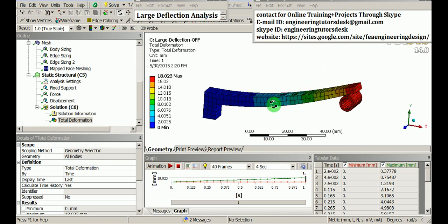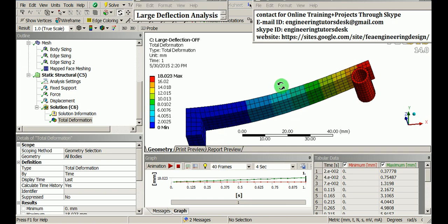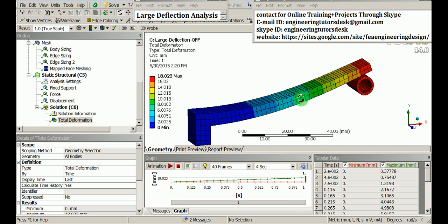This convergence was obtained and the contact was detected. But this is geometrically linear analysis. Let us proceed for the geometrical nonlinear analysis, keeping all the loads, boundary conditions, geometry, materials, and contact settings the same, but changing only the analysis setting.